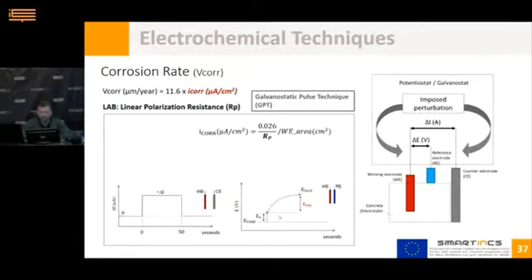As you can see, the ohmic resistance is compensated immediately at the beginning of the test, so that at the end we have the effective polarization, a parameter which, when divided by the applied current, gives the polarization resistance we are looking for. In addition to being simple, this method is really fast, since the pulse rarely lasts more than 50 seconds, depending on the concrete and the steel condition.